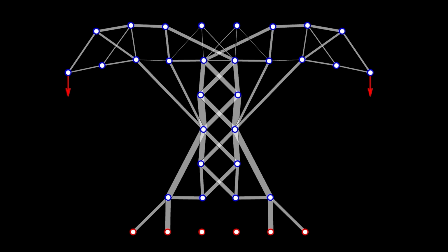that is also robust. In fact, one will see that to really obtain a global robust solution for a certain set of considered forces, one will have to solve an MI-SDP, also called Mixed Integer Semi-Definite Program, which cannot be solved efficiently, and this shows the dependence on an efficient heuristic to approximate a robust solution for the truss. But the robust truss design optimization would be a topic for a video itself and will therefore not be covered here. Basically the idea there is to minimize a truss not for one force but rather for a set of infinitely many forces. The term to minimize is then the worst case compliance for elements from this infinite set.